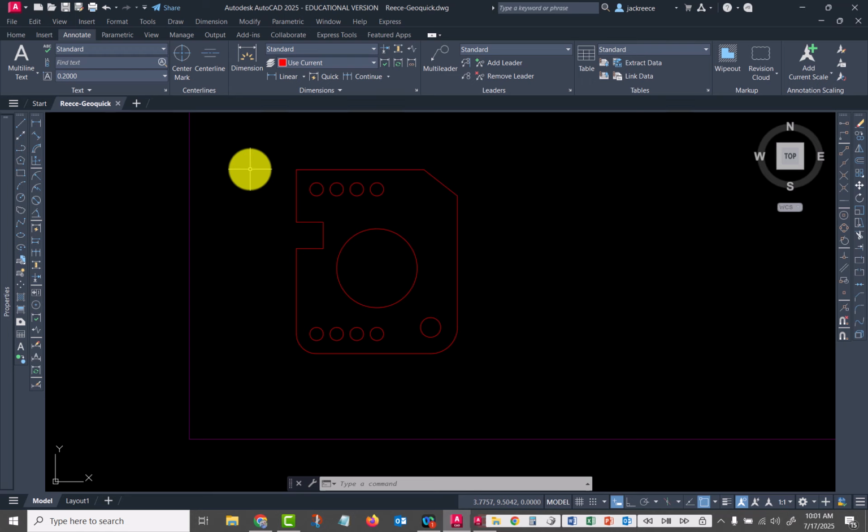So if you set them for an imperial drawing, you would set the size of the dash or the cross to like an 1/8 of an inch, and the overhang to like an 1/8 of an inch or 1/4 of an inch or whatever. But then when you do a metric drawing and you use the center mark tool, those settings are still there. So instead of it being an 1/8 of an inch, it's an 1/8 of a millimeter. So when you use the center mark tools, you have to be careful with those.